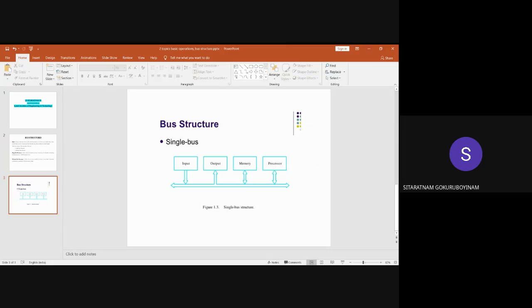The bus provides the communication path between different devices, and can be used for only one transfer at a time. Only two units can actively use the bus at any given time, so the bus control lines are used to arbitrate multiple requests for use of the bus.